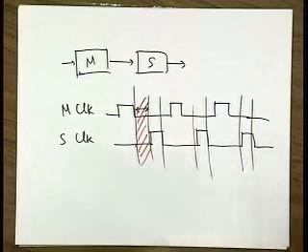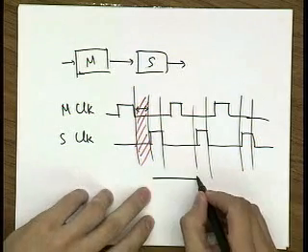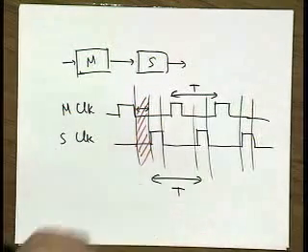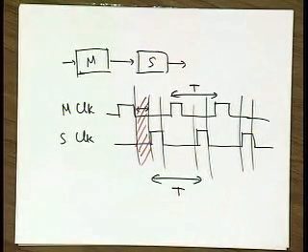If you want to have some spacing between those edges, you need to have different frequencies. No, the frequency is the same. This is your clock period T. This is your clock period T. But it's not evenly distributed. You see the high time and low time. Right, but it's a different duty cycle then. You have pulses. You don't necessarily have to have a 50% duty cycle.